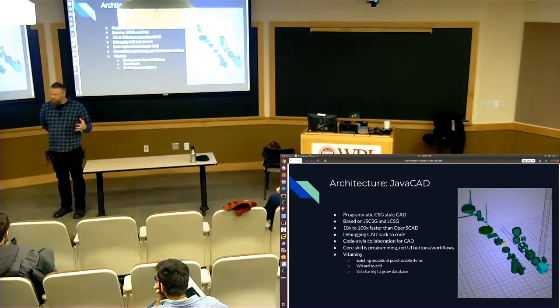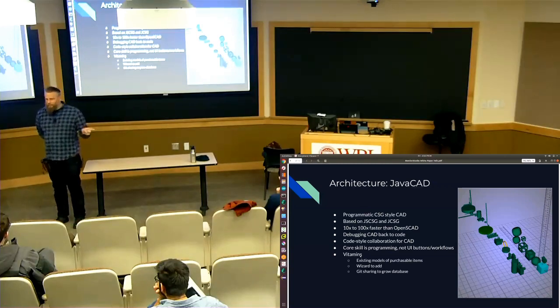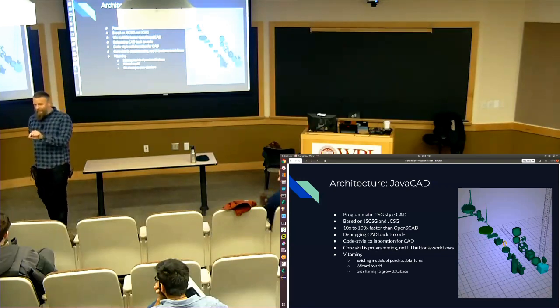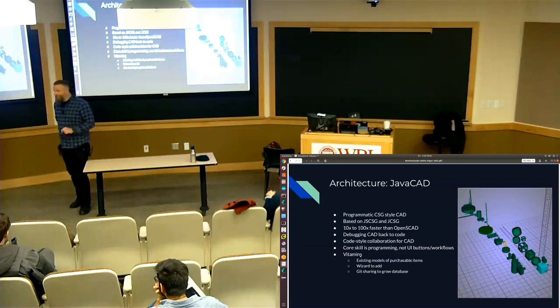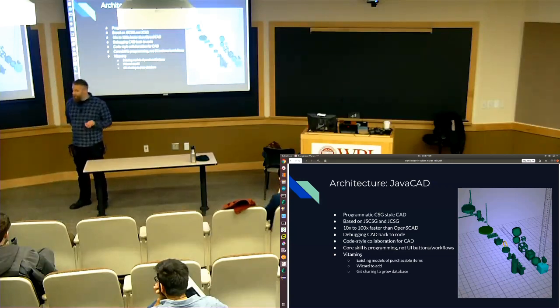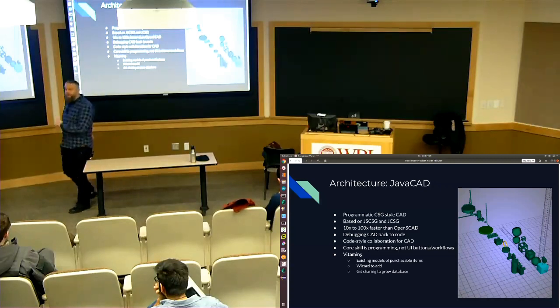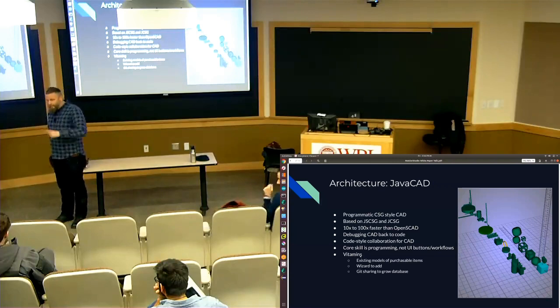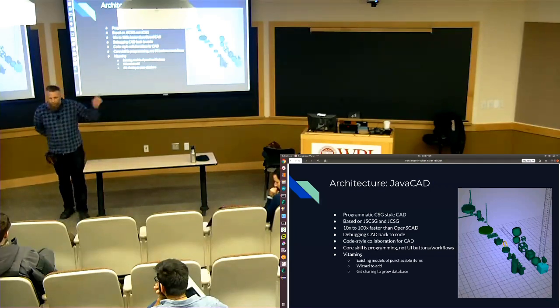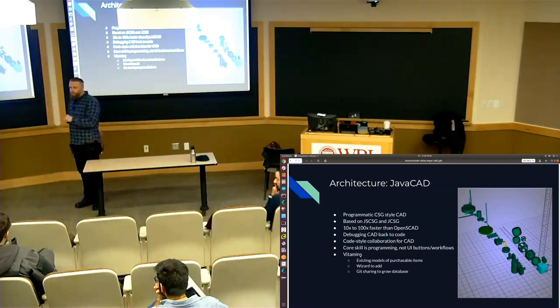There's about 40 or 50 of them. We want to parametrically change from nuts to heated inserts. You can change measurements that way, but shapes, not so much. Parametric on shapes is not something most CAD packages deal with terribly elegantly. And more to the point, because it is essentially a function being called, that cascade does in fact work. Change one measurement in one file and everything that references it works.